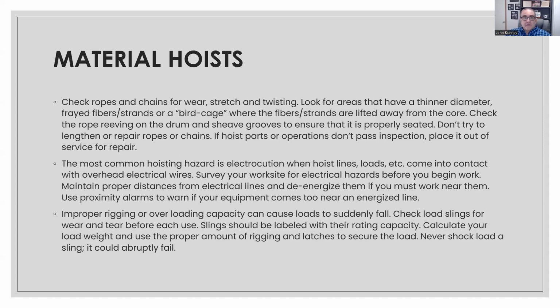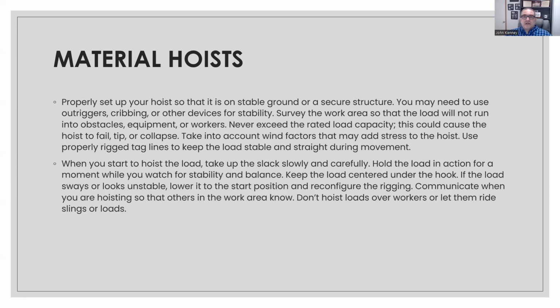Properly set up your hoist on stable ground and a secure structure. So again, with cranes, you want to make sure that you've got a solid substance, your padding, your blocking underneath your outriggers. You're not on soft ground, you're not over top of a septic system, a water tank, gas tank, fuel tank, whatever it may be.